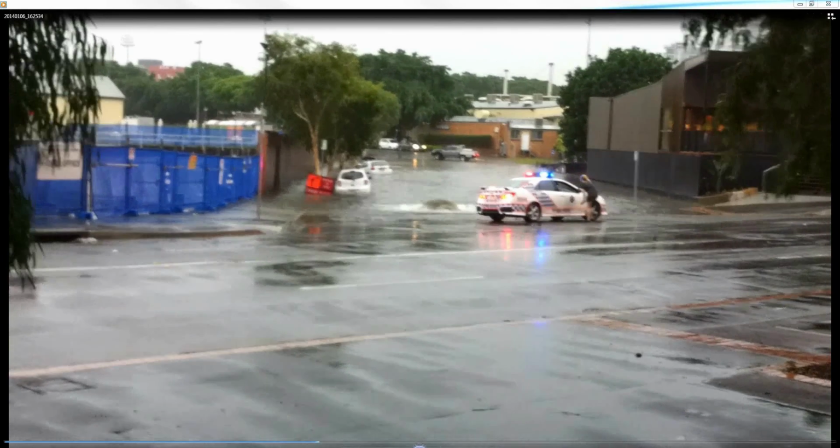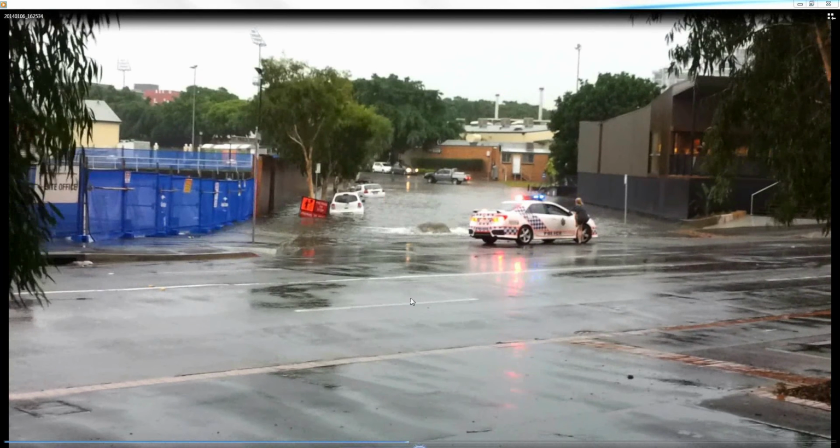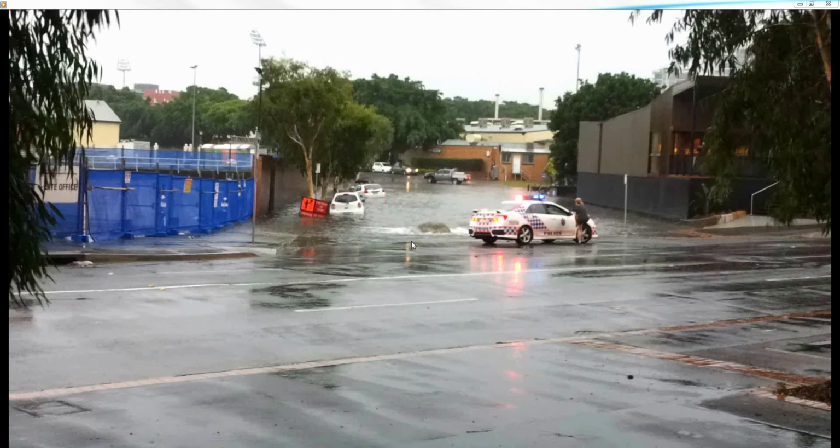And we can see that we have a clear point of surcharge from a manhole in the middle of this road, and from an assessment perspective it would be very important to be able to model this and determine the location of that kind of failure from a modelling perspective, and that could then be used to plan for emergency purposes and either road upgrades or additional pipe upgrades.